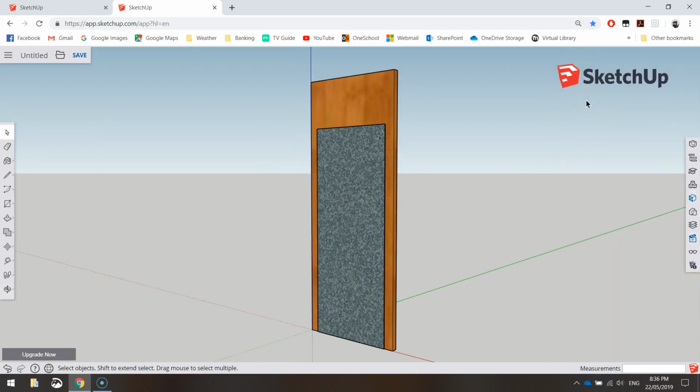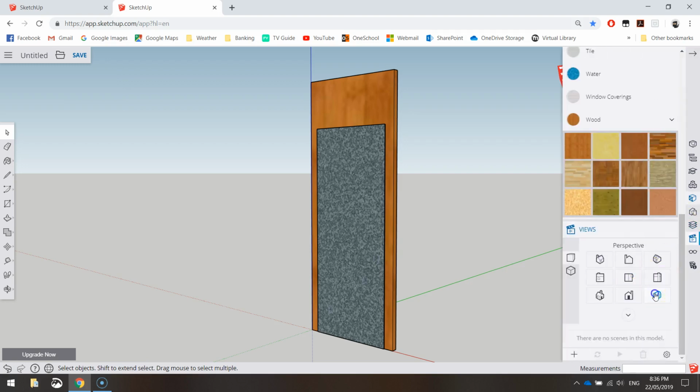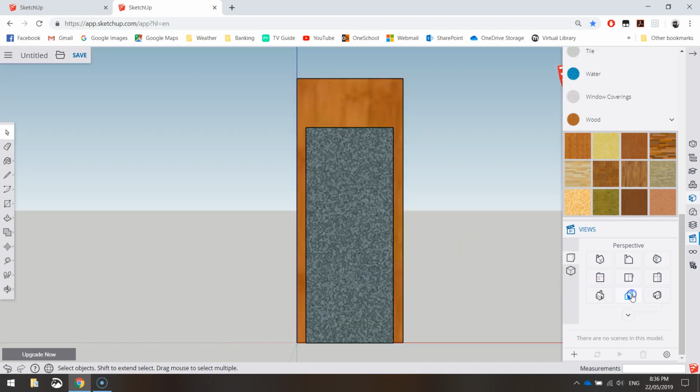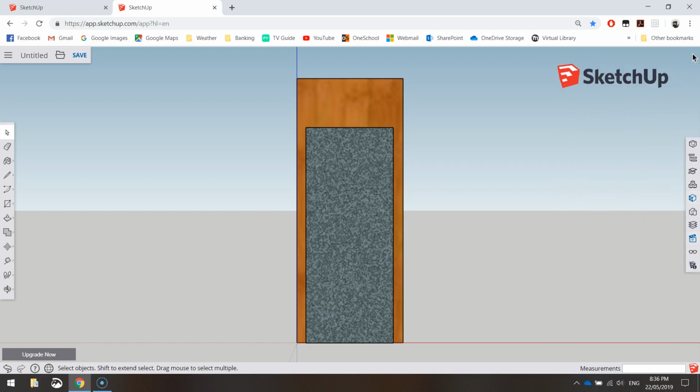The next thing we're going to whack on are some side walls. Side walls are going to run down either side of the mesh. So let's go back to the home view here. Now the side walls are going to start 53 millimeters up from the base. So I'm going to grab my tape measure and click and measure up 53 mil, just looking at the length down here in the corner. When it gets to 53, I'm going to click my mouse, and from there click across to the right somewhere. I just want to get that dashed line appearing, which is going to help guide me when I do these side walls.